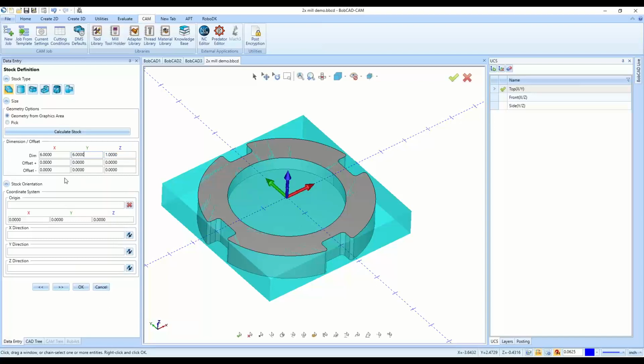If I only want to add a certain amount in one direction, that's where these offset options come into play. If I want to add in the X direction an extra 1/4 inch of material, I can just add that in, hit the tab key to update, and we've got that extra 1/4 of an inch in the positive X, and now in the positive Y direction, instead of adding any in the negative X or negative Y direction here. So I'll just hit 0, even everything up.